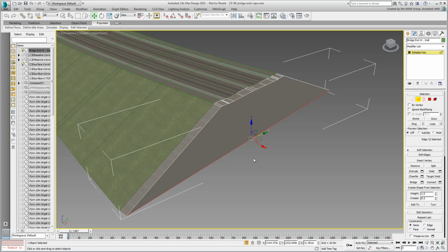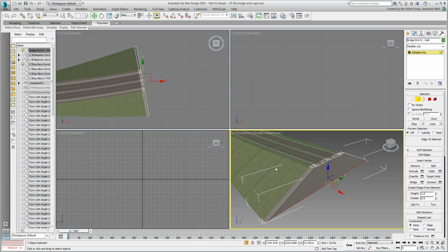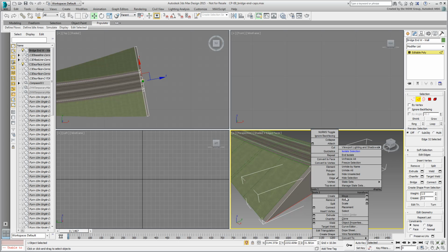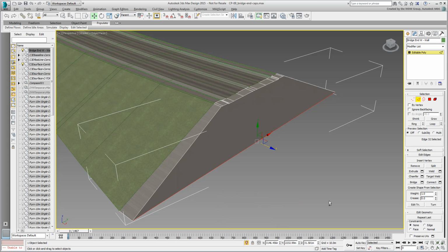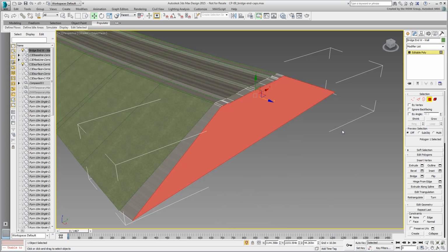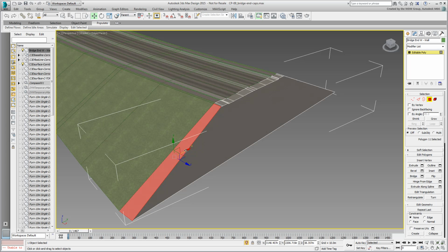For that, you'll need to set the coordinate system to Parent so that the edge conforms to the orientation of the new wall. Similarly, you may consider a slight relative X displacement of the sloped polygons so that they are not flush with the grassy part.